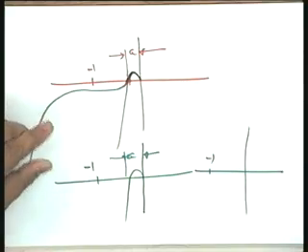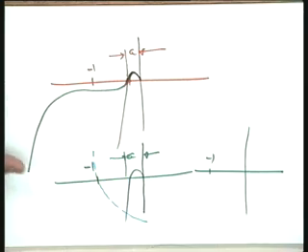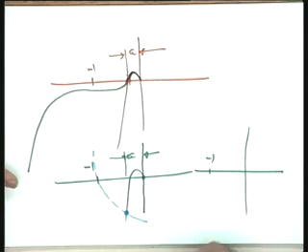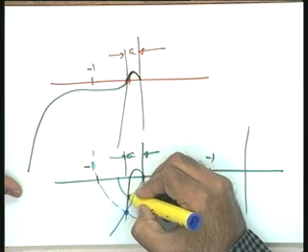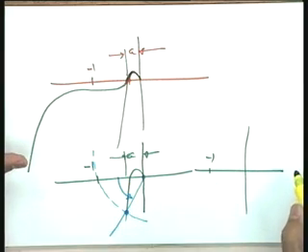The other index, to see the phase angle, is this: you just draw a unit circle with this origin as the center. That is, you locate a point here on this particular curve where the magnitude is 1. This particular angle is also a measure of closeness of the plot to the minus 1 plus j 0 point.